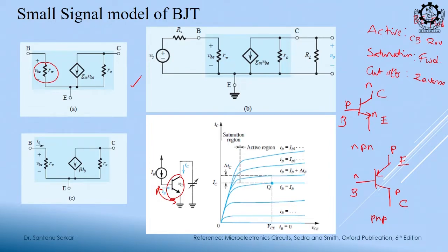Let us define this. Now, I have a dependent current source, right. IC is equal to beta IB, that is it. This is my base current, this is my base terminal, input side; output side is my collector. So, what is the collector output current? IC. The relationship between IC and IB is beta IB. So, this dependent current source has a gain of beta, and it depends on this current, just that.